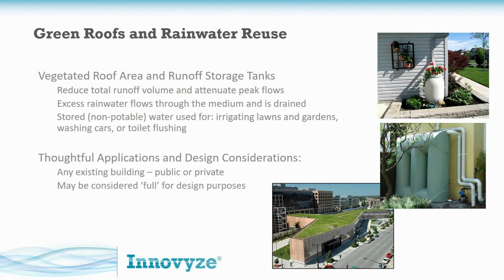The item here, though, for rainwater tanks in particular, they might be considered full during your design, right? Like the absolute worst case scenario is that it rains a little bit and then 2 days later it rains really hard, right? So that first rain fills up your rainwater tank, then the proper rainfall event hits. So, in many cases when you're designing, your rainwater tank isn't allowed to be used for a volume reduction device. And if you are designing this, well, you've got to take into account the drawdown rates, tank volumes, and really what kind of overflow structure you're going to have.